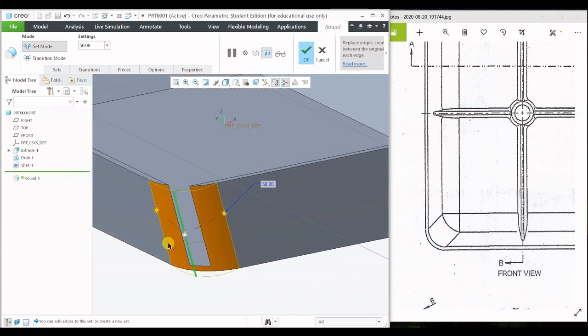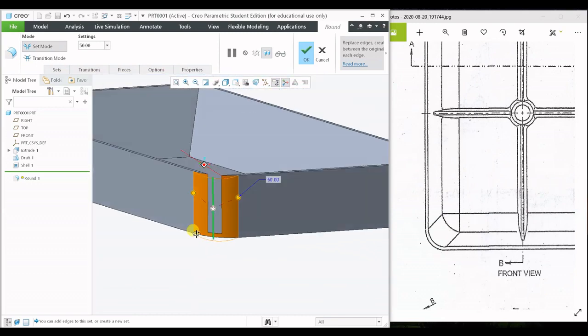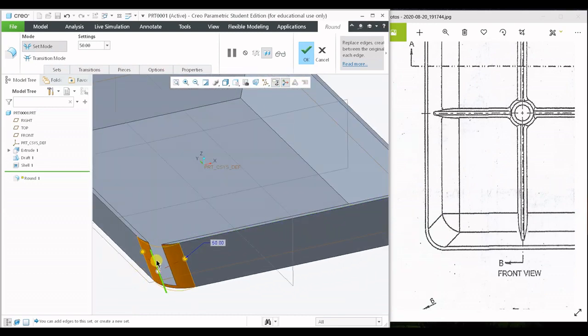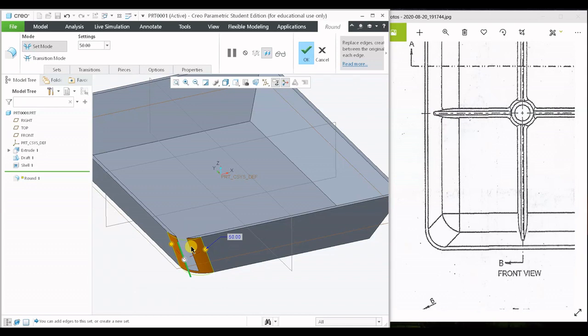It is getting eliminated or it is getting deleted. So it is basically getting removed because the thickness of the wall is very lower than the rounded dimensions what we needed for the geometry. So in order to create a rounded geometry for this shell component, it was better for me to create the round before creating the shell.